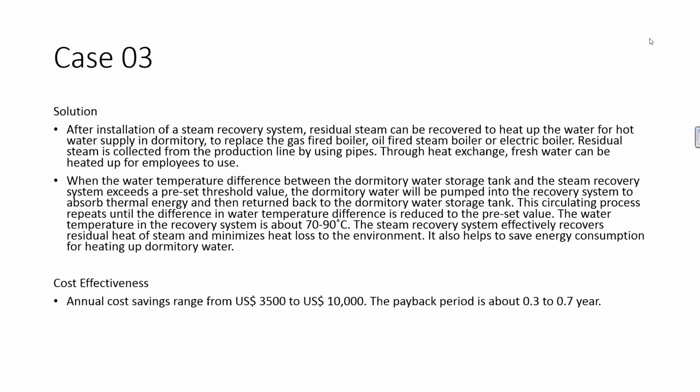The solution for this: after installing a steam recovery system, residual steam can be recovered to heat up the water for hot water supply in the dormitory to replace the gas-fired boiler, oil-fired steam boiler, or electric boiler. Residual steam is collected from the production line by using pipes through heat exchange. Fresh water can be heated up for the employees to use.